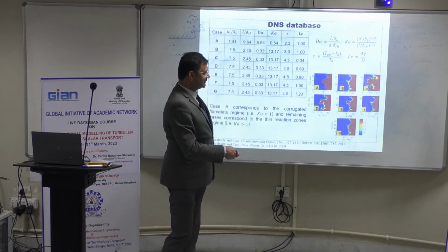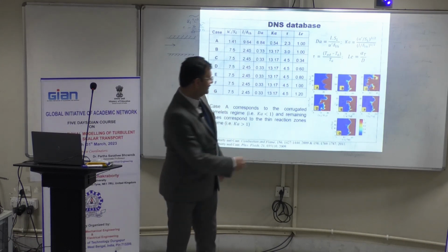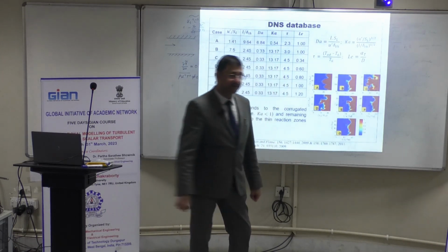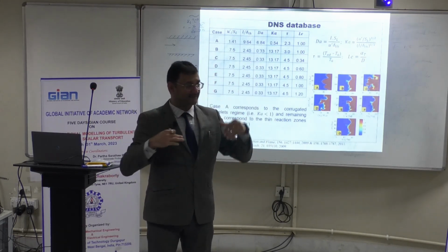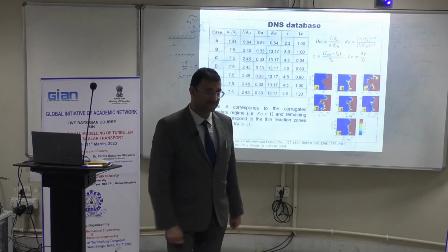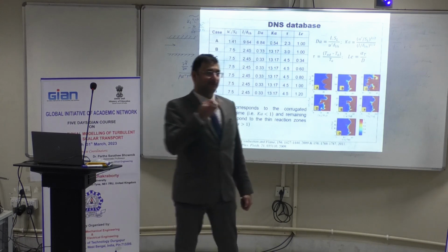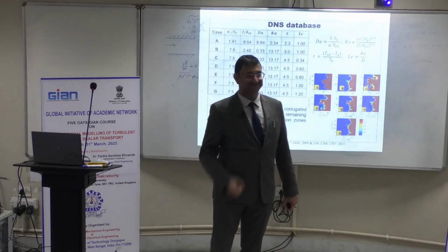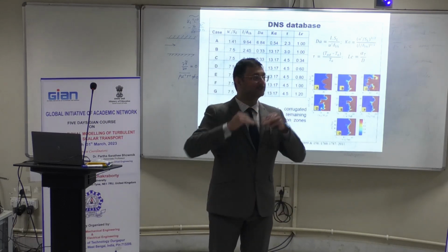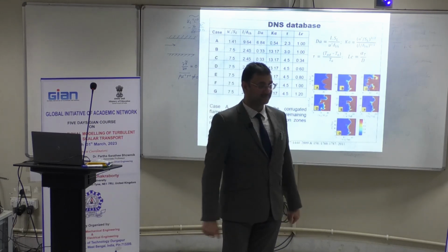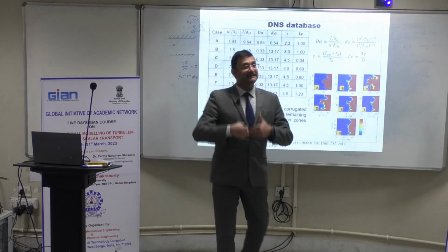Just the opposite thing happens in the case of Lewis number greater than 1. Where it is convex towards the reactants, heat is diffusing out faster than the reactants come in. So now I have low temperature, low reactant concentration, and the reaction rate drops. It does not propagate that fast. So it has a stabilizing effect, whereas Lewis number less than 1 has a destabilizing effect.